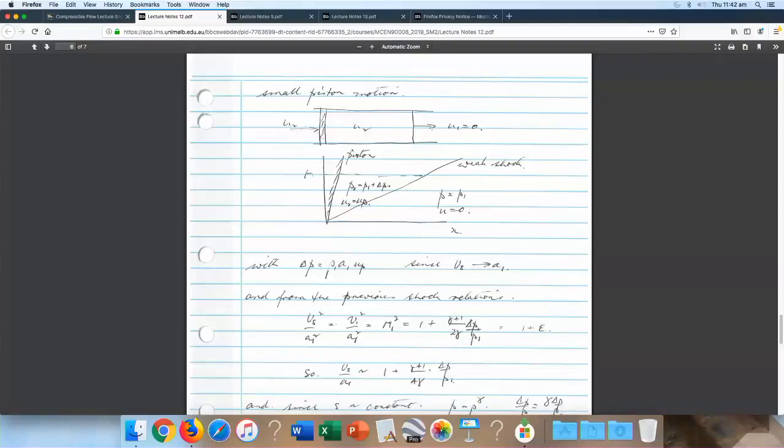And it's an approximation that the pressure can't adjust through an expansion wave. This is not a supersonic flow. The flow is only moving here at the velocity up. U2 is equal to up. So it's highly subsonic flow. In a highly subsonic flow, the flow is going to be accelerated by the pressure gradient, and that's going to drop the pressure. So the pressure at the exit, to a first approximation, is atmospheric pressure.